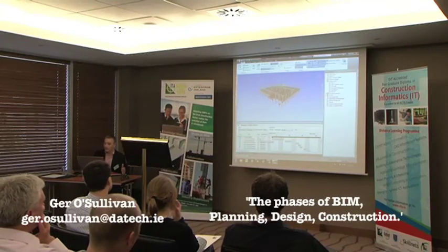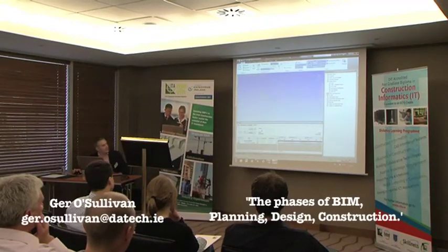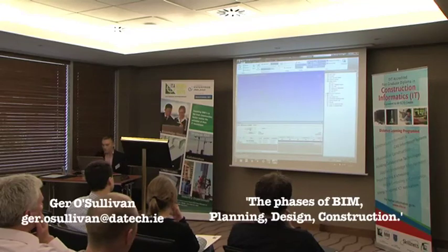We can then link the objects to the tasks, and then what we can do is simulate those tasks. So I'll just zoom in a little bit so you see it happening. When I go back to the simulate button, let's just start it off. At the moment, the foundations are being poured, we'll say. Whatever is green is being worked on. And then we can play through that simulation. So again, as you see the model developing, you can see it live on the screen.